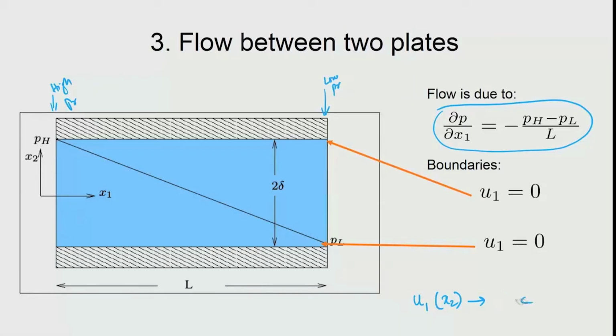Okay. So, the boundary conditions are given as follows. So, the velocity at the top wall and the bottom wall are both 0, because both are stationary walls, and from the no slip condition you have that 0. Now, we need to choose how to place our axes. So, the coordinate axes are placed in the center, so that the plus delta and minus delta will become the two walls. Okay. So, this you could say is at plus delta, and this will be at minus delta. So, there is a certain symmetry in this problem. We want to exploit that by simply also choosing the distances appropriately. It is not important when we plot it, but while deriving actually such simplifications make the algebra a little easier.